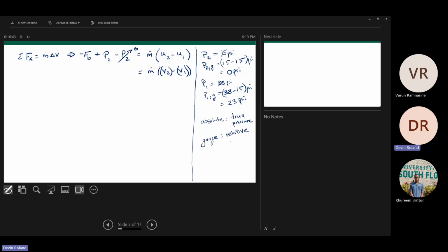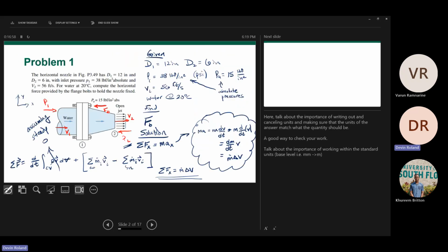So this is relative with respect to atmosphere. Yes, what I was saying is that we have these two pressures, on the left and the right. But P2 is where the flow is exiting the nozzle. And so P2 is equal to this P ambient, P atmosphere.